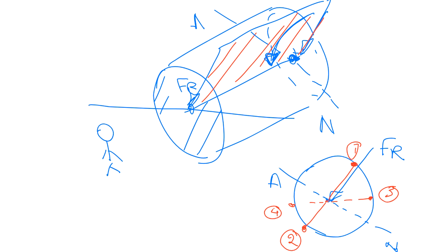When you say tension or compression, your neutral axis is no longer vertical or horizontal. For example, if I need to calculate the distance between point 3 and the neutral axis, I have to project point 3 onto that neutral axis and measure this perpendicular distance, which is y3. You got this one, guys? And because of the symmetry, your y4 will be equal to y3. So I can claim that the stress magnitude at 3 and 4 are equal, but one of them is tension and the other one is compression. Do you all agree about this, guys? Yes, doctor. Okay.